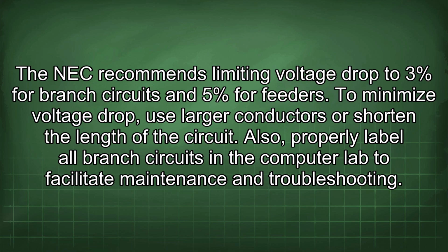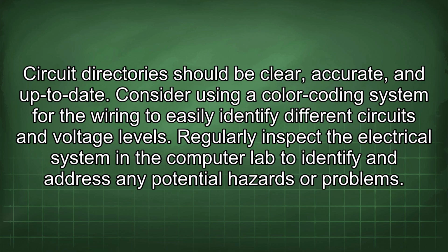Also, properly label all branch circuits in the computer lab to facilitate maintenance and troubleshooting. Circuit directories should be clear, accurate, and up to date. Consider using a color coding system for the wiring to easily identify different circuits and voltage levels.